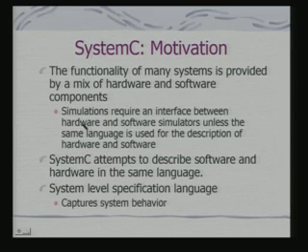The simulations would require an interface between hardware and software simulators unless the same language is used for the description of hardware and software. So, this becomes a constraint. SystemC attempts to describe software and hardware in the same language.